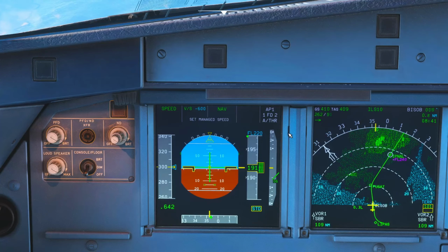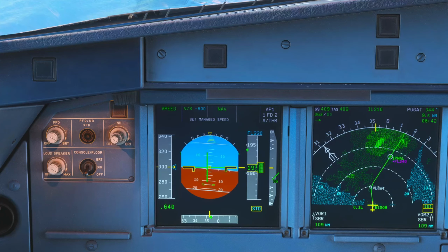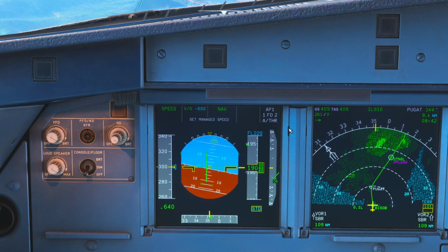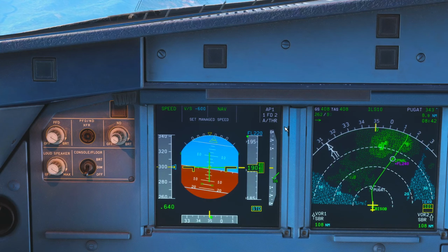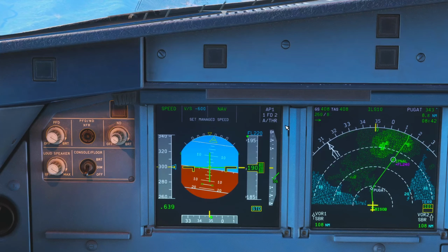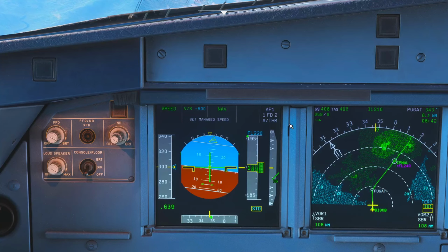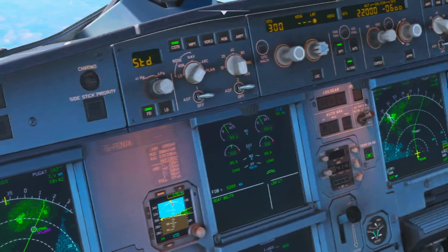Have to limit first airspeed above the stall speed and below maximum speed. Check you are not currently flying too fast for the flap setting you have. Check flight control inputs are neutral and the aircraft is trimmed. The aircraft must be in the air at least 100 feet above the ground after takeoff or 400 feet prior to landing.